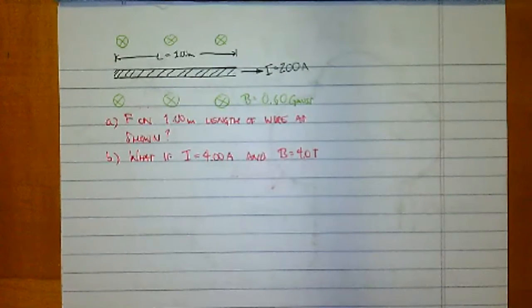Now, how did I come up with that 200 amps? Well, it's not uncommon for a wire that you might see going across the country field, the ones that are really high on the tall towers, to be carrying enough electricity for, say, 10,000 homes. If that's the case, every home gets about 200 amp service. So 200 times 10,000 gives you about 2 million amps.